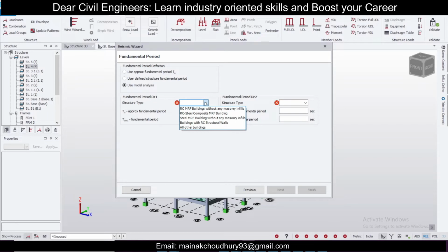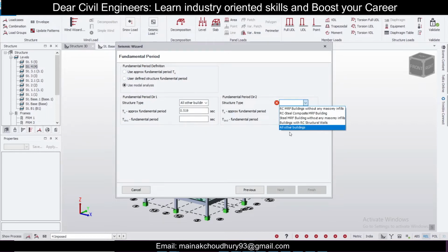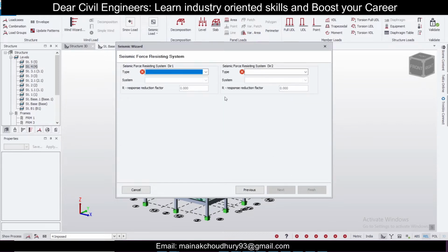We're using RC. These are the options here: RC moment resisting frame without any masonry infills. We'll select all other buildings here, and after that click on next, and here you can select moment frame systems, structural system 1. So we'll select moment frame system, and we'll select RC building with SMRF here.